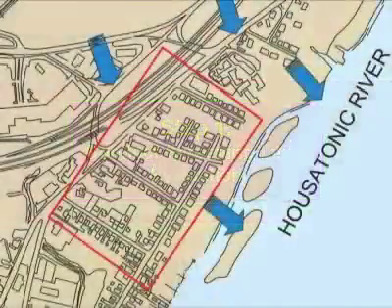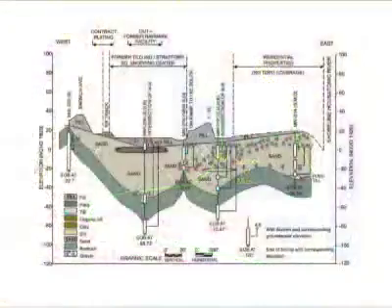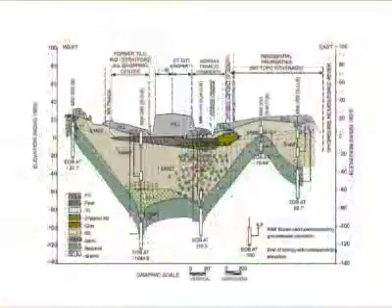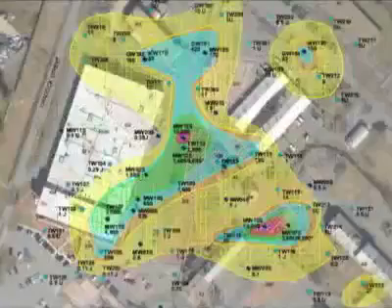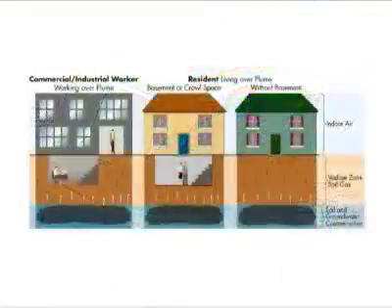First, develop a conceptual site model, or CSM, to describe the site setting. The CSM is typically a visual portrayal of site conditions that helps with the understanding of contaminant sources, how they move through the environment, and the ways people could be exposed to them.